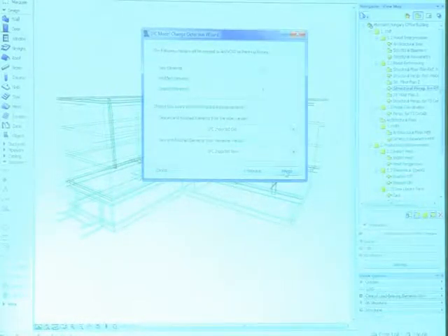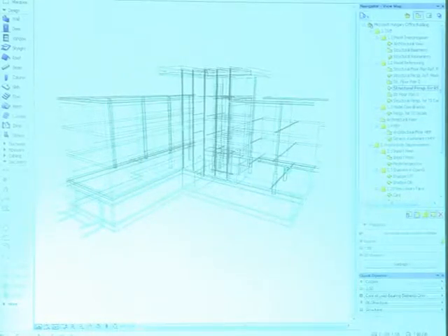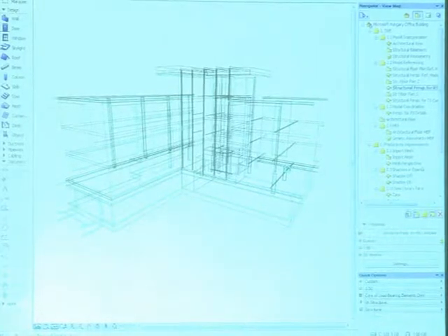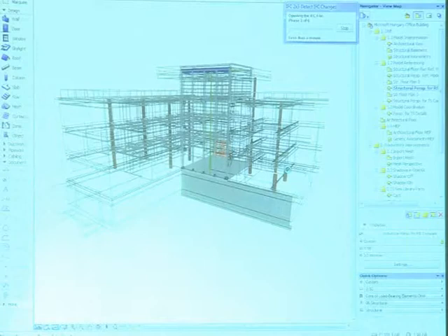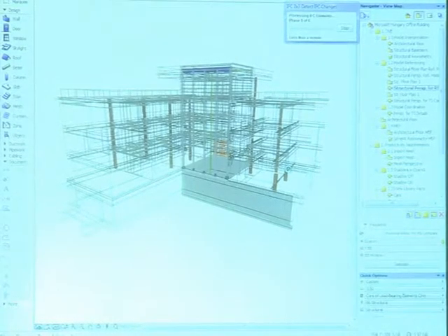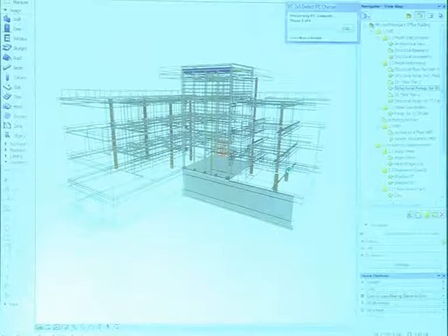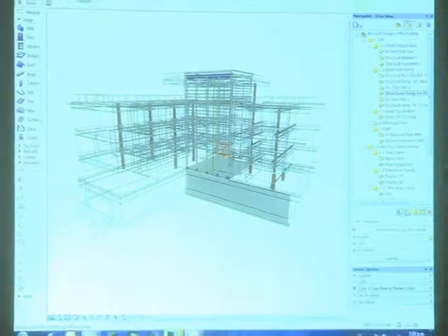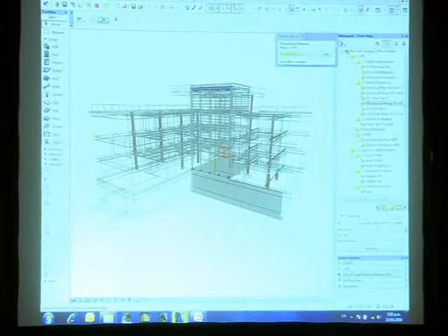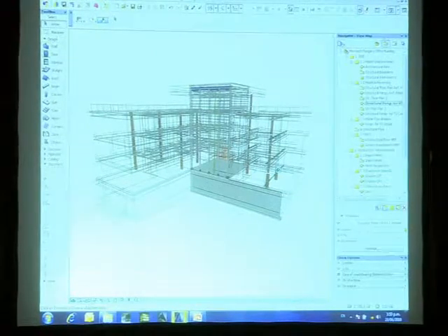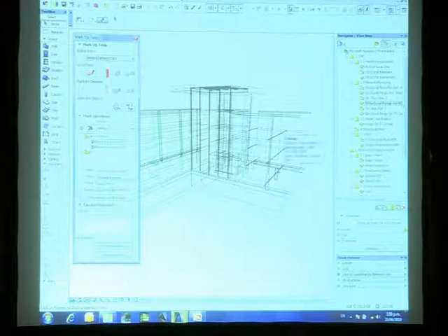And it writes out, as I've showed you, two new elements, one modified, which was that central brace, and 4 deleted, which were the 2 columns and the 2 beams. Now let's see how it looks in reality. So now for a few seconds, ArchiCAD starts a little bit thinking. We'll switch on and off layers here, because it compares in the 3D all the elements and all the changes that have been done. And now it will merge in only the changed elements, which will appear in the markup.